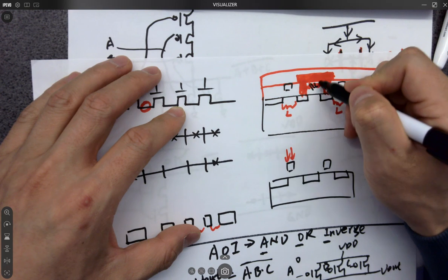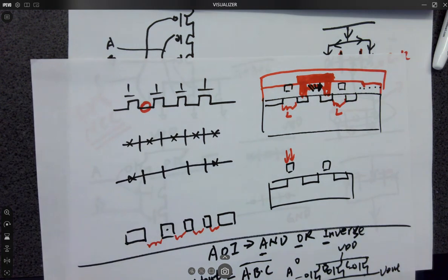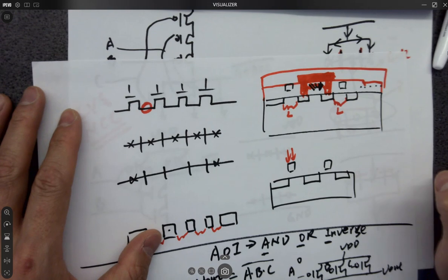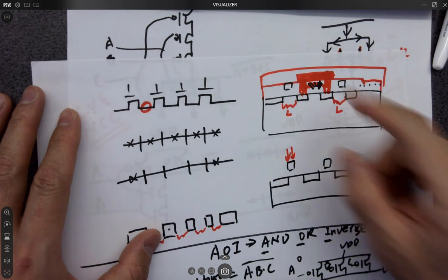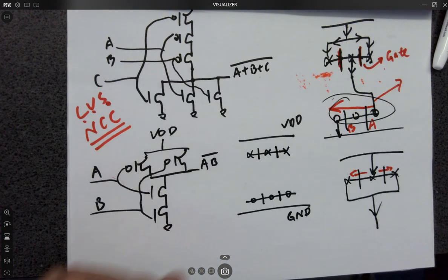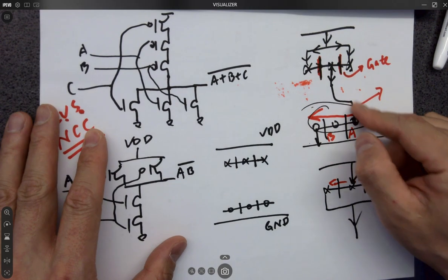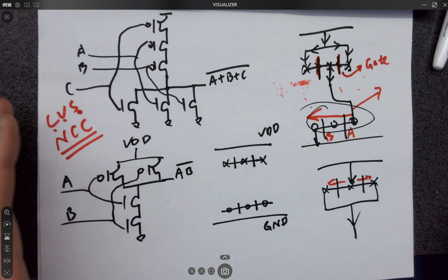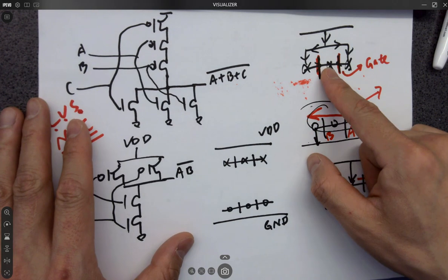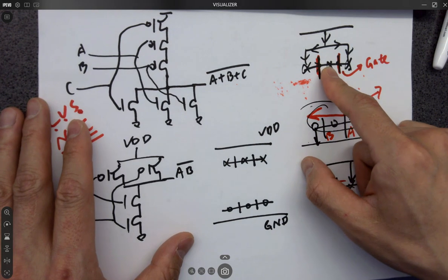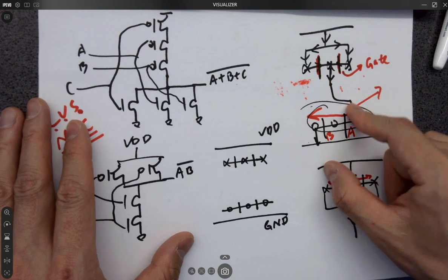There's nothing that can be an arc in the circuit, right? In the IC. What is that wire? Metal 1. Okay, it's metal 1. So what is this wire? It's going to be metal 1. Has to be metal 1. There's no poly. Poly is a gate. It's not a gate, it's a node. So a node needs a via to be shorted to metal 1. So this has to be metal 1.